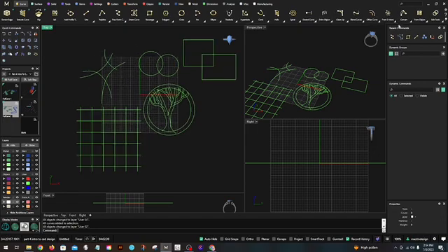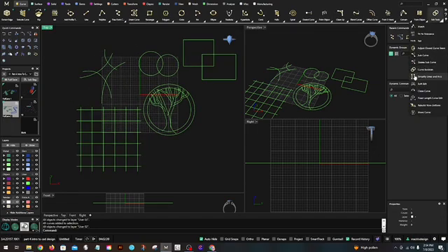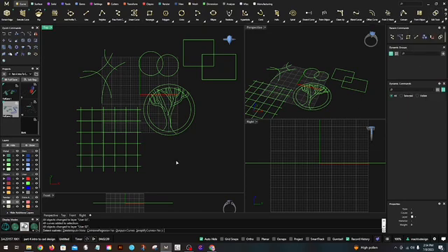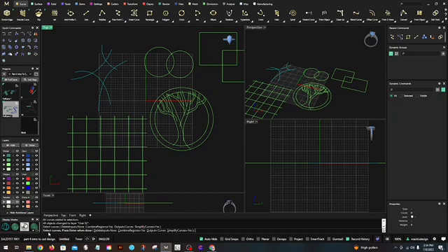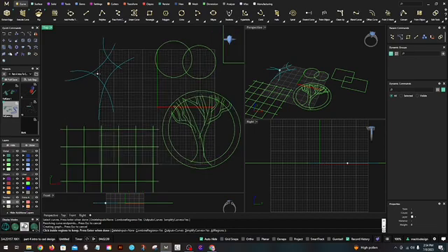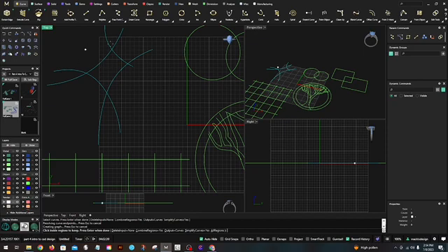And I am going to go back up to my curve boolean, select that. It wants me to select the curves. I don't want to delete the output. You can if you want. So I will select these to begin with. And then you want to press enter. And then it's ready to actually do the action. And what you want to do is select inside the curve region that you want a new curve to be.